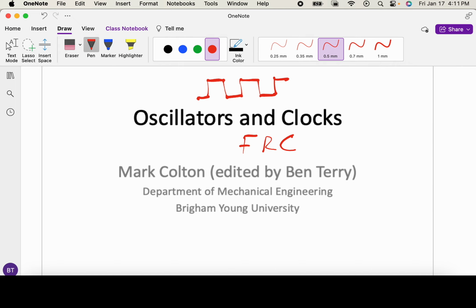So off the top of my head, I think your timing will be within maybe 1 to 5% of what you think it should be. So generally, for very precise timing, you use a crystal, but for our use, this is perfectly accurate enough. And FRC oscillators are typically used for cost-effective applications or a fallback if an external oscillator fails. So basically the trade-off is it's faster to start up and it's cheaper, but it's less accurate compared to crystals or crystal oscillators.